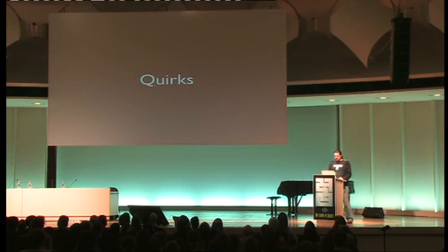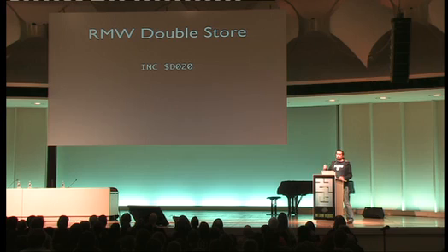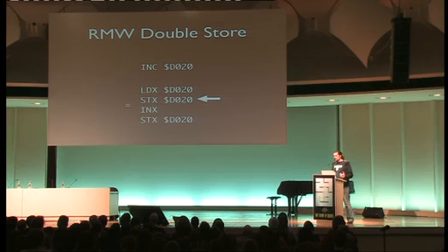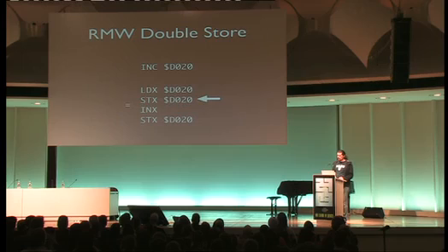So the 6502 has some weird things about it. Some you could consider bugs, some just, well, you don't care, but why do they happen? So for example, if you increment something in memory, what you would expect is you read it, you write it. But what happens is it reads it, it writes back the original value, sometimes within those 4 cycles, or 6 cycles, and then it stores the new value. So from a software perspective, you cannot see the difference, but from a hardware perspective, you can measure that. And you can build a computer around that, and you can make use of that oddity and build your copy protections or obfuscation around things like this.